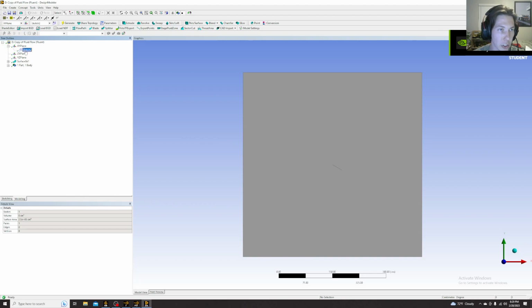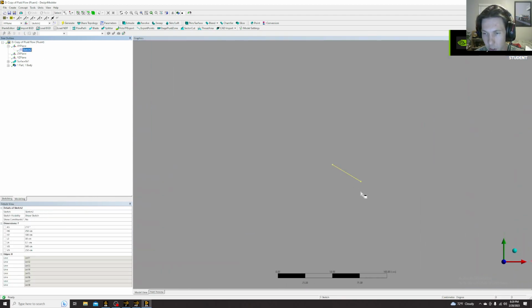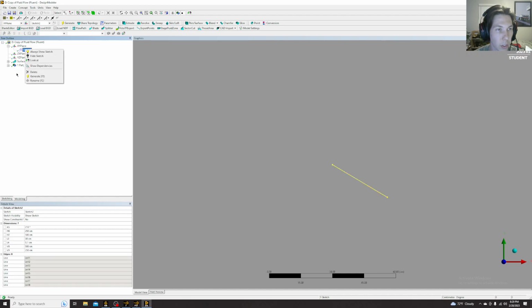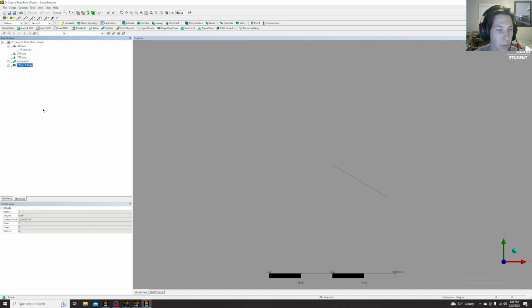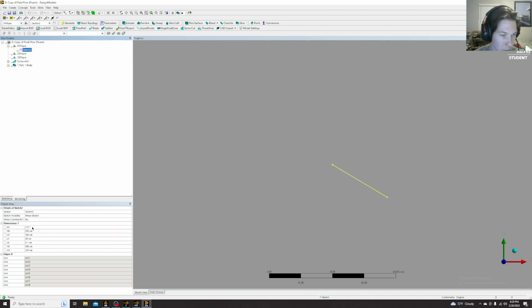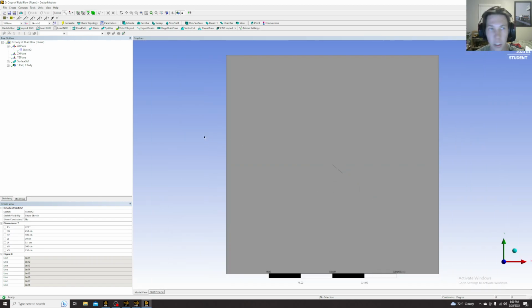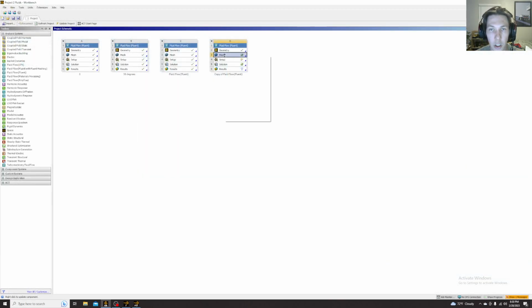However, let's say we want to change the angle. So we'll go to this, zoom in. Okay, so instead of 210, let's say we want to make it like, I don't know, a 40-degree angle. We'll go to 220, slightly larger angle, generate that, and that's literally all you have to do. So now you exit out of the geometry, come back to your mesh. Actually, you probably go to the results, honestly. Update.